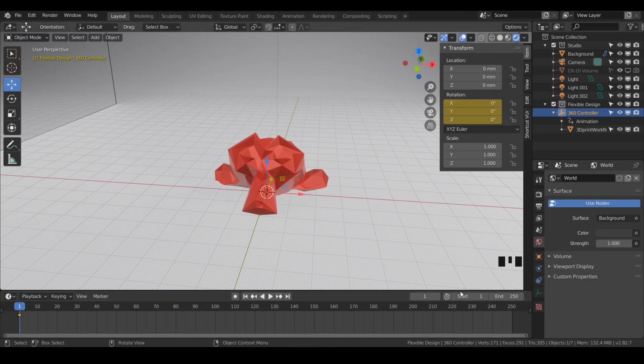Then, let's say we want this rotation to last 5 seconds. We can tell Blender how many frames we want in our animation. If there's 24 frames in a second, we can just type in 24 frames times 5 seconds right here in this side, hit enter, and then Blender will do the math. So that's 120 frames. Thanks, Blender.